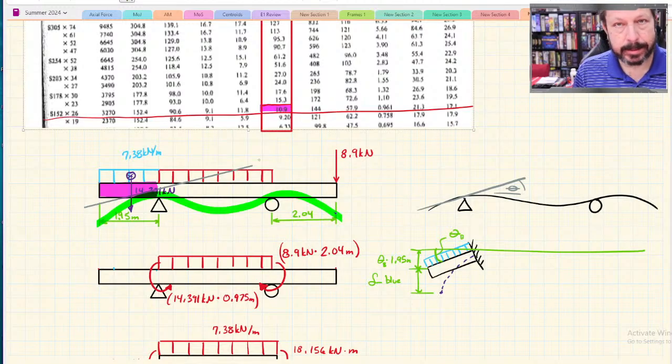This slope is constantly changing. And so that's why it maybe makes sense that I calculate the slope at one point to see which way it started heading, but then it keeps bending based on the equation of the elastic curve that I'm going to use, or the deflection equation.